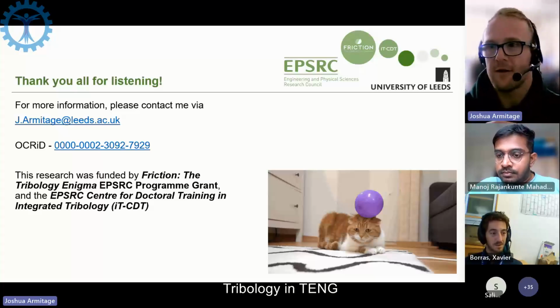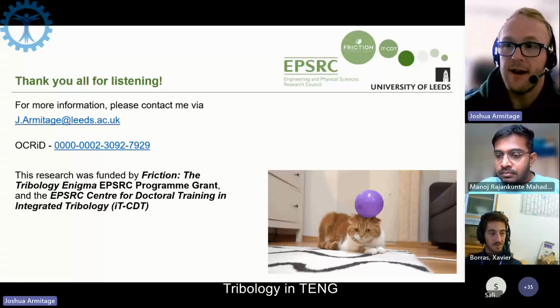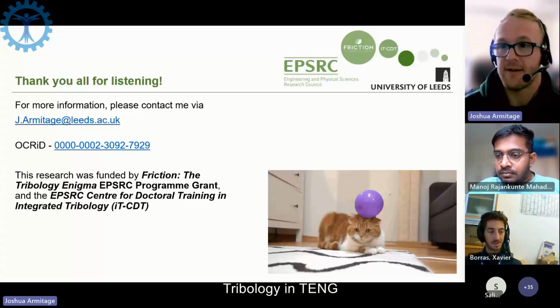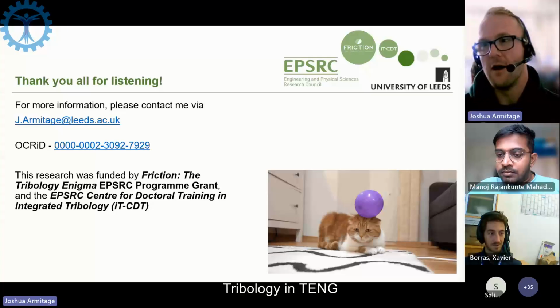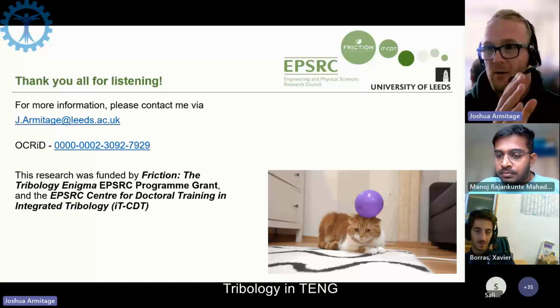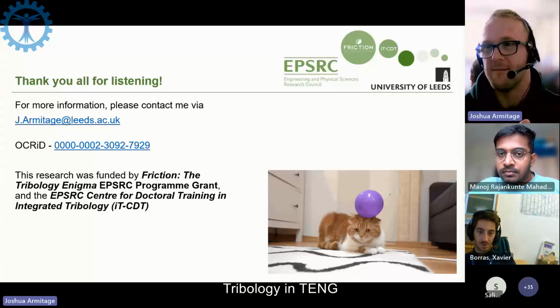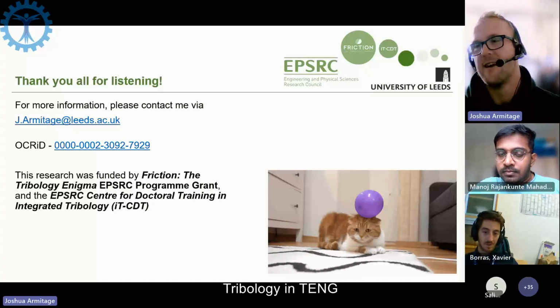You have the entrapment of electrons. For example, in PTFE, they become donated to the carbon backbone because that's where a lot of low energy unoccupied electron states are. So those electrons are retained quite well within the Teflon. Teflon is a material that really loves to hold on to its charge over time, and it makes it quite difficult for me to test with in terms of removing that charge before I start a test.